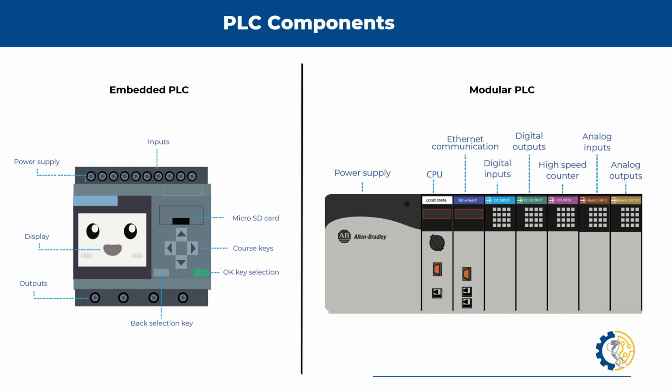So what good is our memory or the slot for my micro SD? Well, in case of an emergency, we can actually have a backup for my current PLC program, and I can store it in case of an emergency. In case something happened to our PLC and we modified something or it's doing something strange, we can input it. We can enter it.